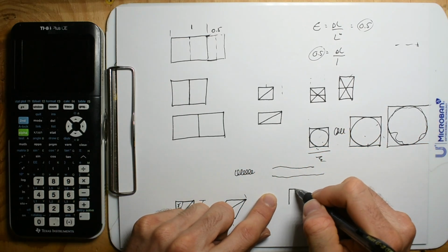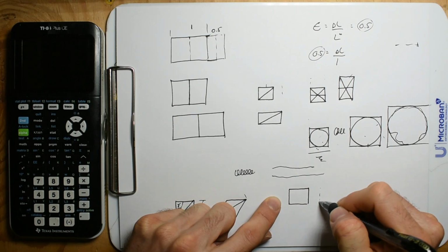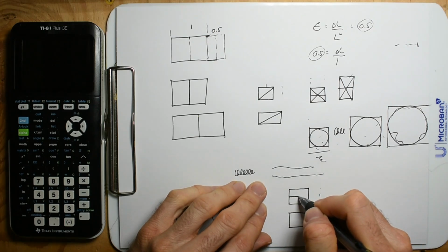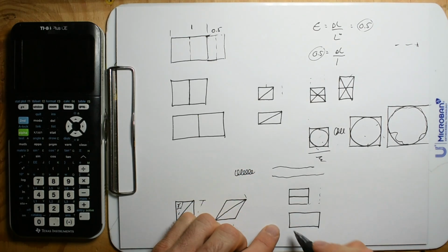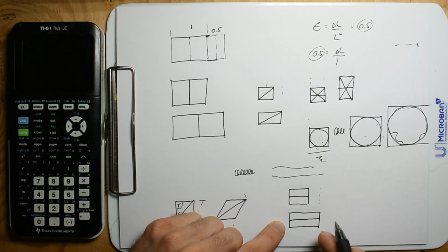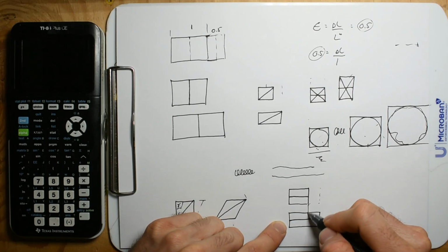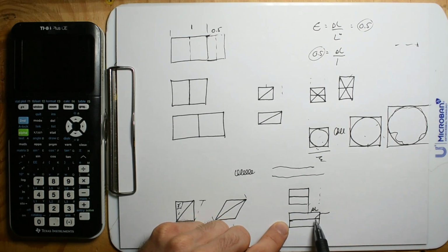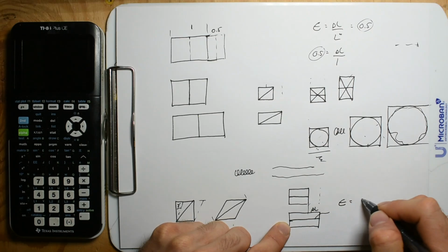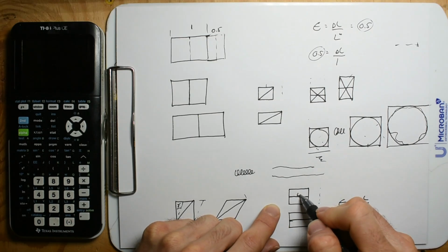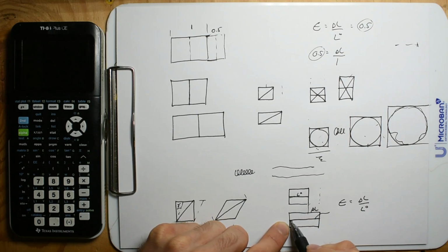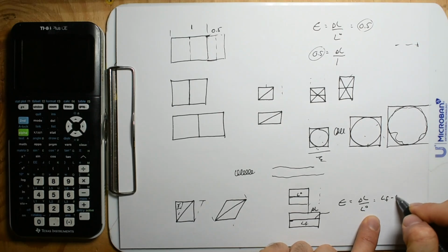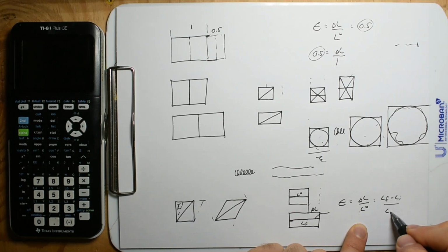Now, check this out. Yeah, this is good. Because if I go back to this X, and I know it can double this way, what happens if I just draw a straight line? I paint a straight line like this, and then that straight line is going to be right there. What happened to that straight line? That straight line for sure changed in length. And this straight line is giving you a visual representation of strain: change in length divided by initial length. This is the initial length of that line. This is the final length. And so I know the change in length because that's length final minus length initial. And then this is length initial.